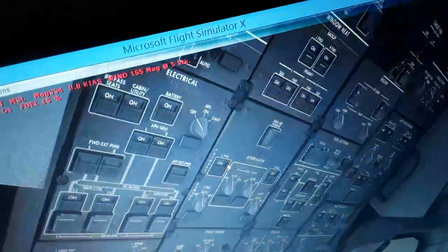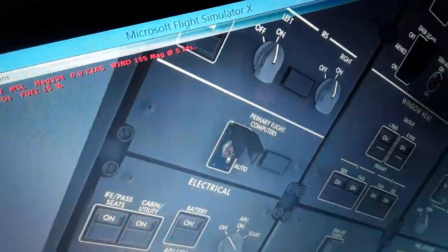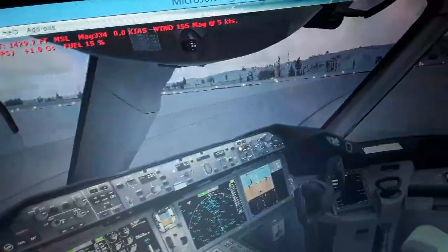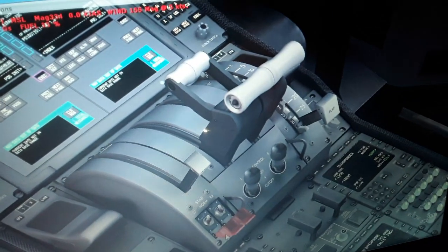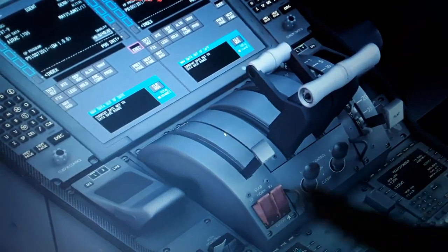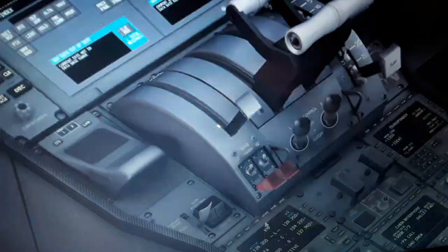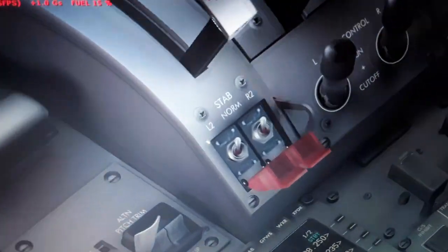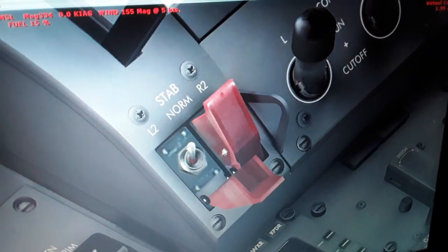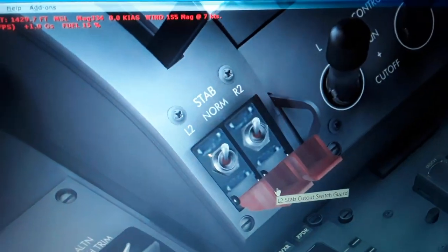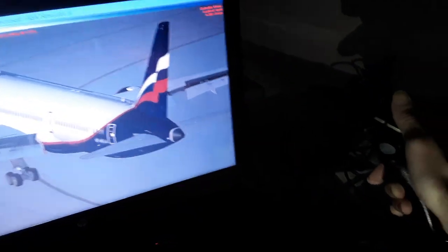It will degrade the modes of the flight control computers from normal to alternate or direct mode. We'll lose the autopilot because we won't have the automatic trimming. We need to come down here. This is for Boeing 737, Boeing 747, Boeing 757, Boeing 767, Boeing 777, and Boeing 787. You move from normal to cut off here and disconnect the auto trim function. As you can see, normal to cut off, either the left tail or the right tail with auto stabilizer.